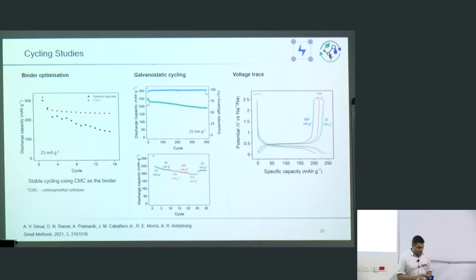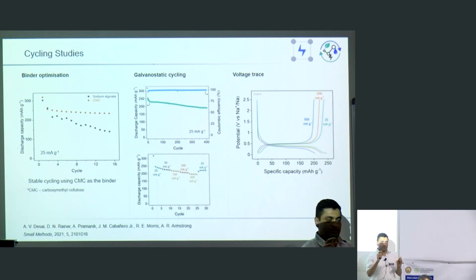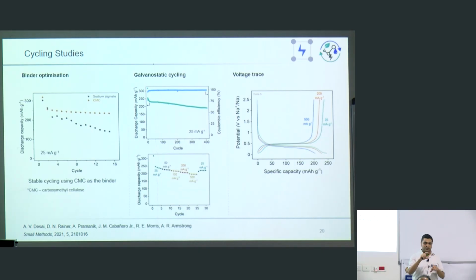The other key thing when you are producing a new material is to look at current voltage profiles, right? We all know or have seen it before. This is slightly different. On the y-axis, it's got a potential, but instead of current on the x-axis, it is showing capacities. But in this particular example, with the mechanism that I showed, the ion insertion happens at the carbonyl site.